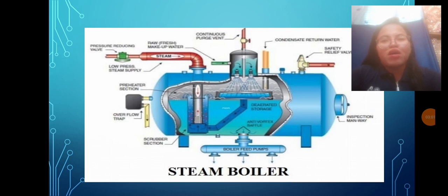The process of changing water into vapor is produced by heating the water in the tubes with energy from the burning fuel. The combustion process is carried out continuously in the combustion room with fuel and airflow from the first surface. The resulting steam is superheated, with high temperature and high pressure. So the amount of steam production depends on the surface area of heat transfer, flow rate, and heat of combustion applied.